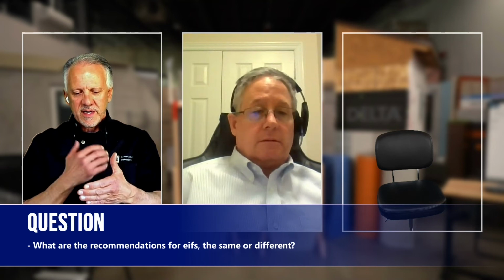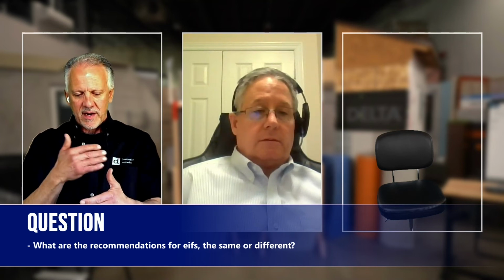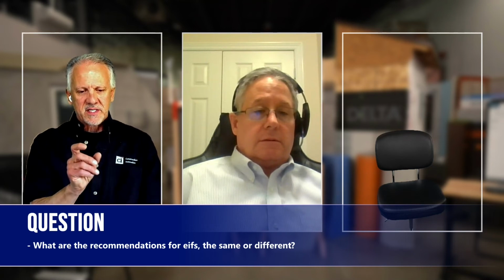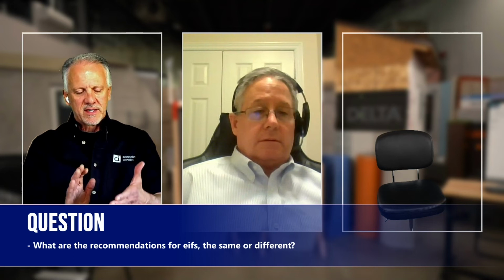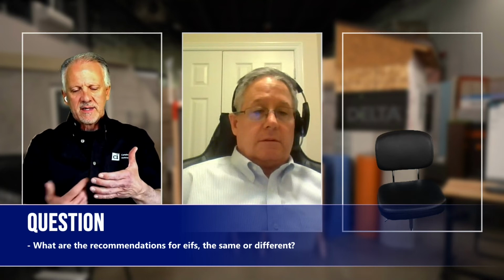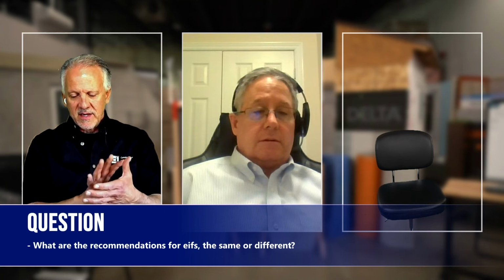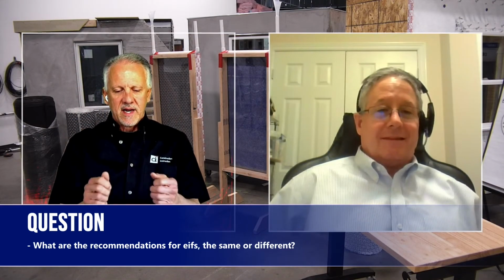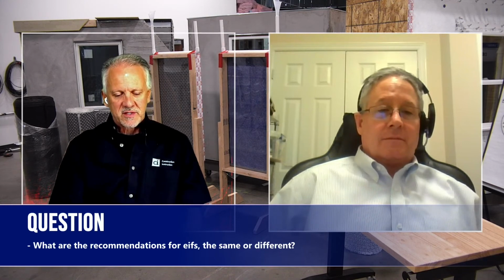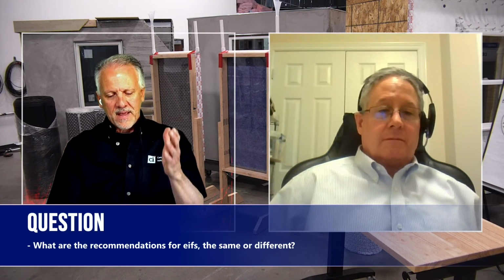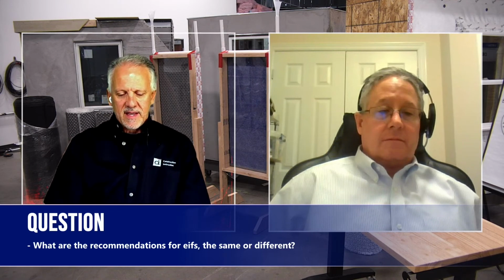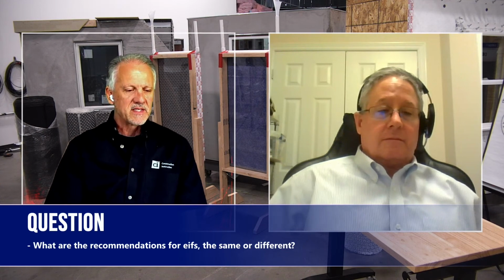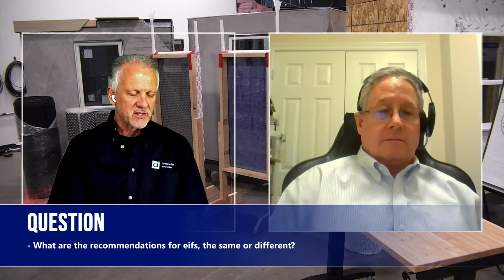Here in the Southwest, through California, Nevada, and Arizona, we would see a 3/4 or 1 inch piece of expanded polystyrene. A pretty low density product would then be installed and just nailed on. Then they would lath on top of that, oftentimes with paper there, and then scratch right to the lath. In those applications there's really sheathing and your drainage layers in play. If the foam layer is installed, you then put the stone and lath on top of that, and then scratch to that surface as well.